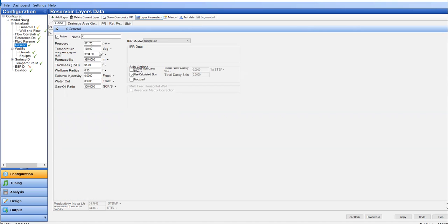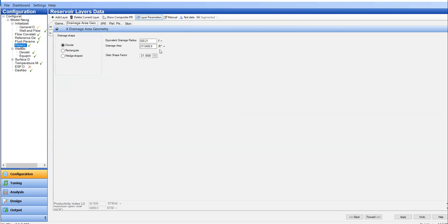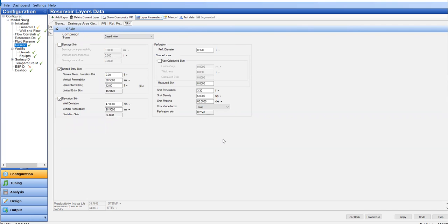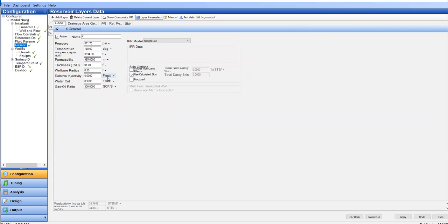You can do the analysis, you can make assumptions, you need to calculate, for example, you estimate the drainage area of your well. You also need some assumptions for the skin factor modeling. You need to provide all of that information into the software until you finally arrive at generating the IPR. All right. But you can also construct the IPR using well-test data.